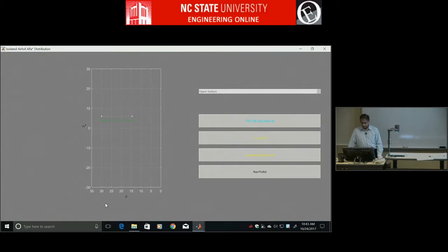Or you can plot the lower surface. In a cambered airfoil, you can toggle this and go to lower surface and plot that. For a symmetric airfoil, all you have to do is define the upper surface and everything is automatically defined. And again, the dashed white line is the previous airfoil, the current one is the green line. Even here you can zoom in, and you'll see that this was 6 and then you made it 4 and it's come here, right?